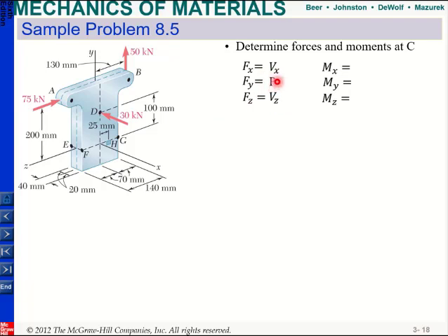So you will have a P, this normal force. It can be tension or compression. And if you have forces along X and Z, they will be your shear forces. So Fy is the normal force, which will create normal stress. But Fx and Fz are my shear forces, and they can only create shear stress. On this line, I will do the same thing since this is my normal axis. If you have a moment along the Y direction, it will be your torsion, and Mx and Mz will be your bending moments. So torsion creates shear stress, and Mx and Mz create normal stresses.